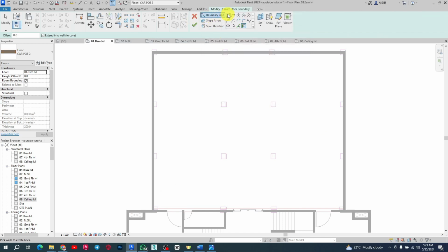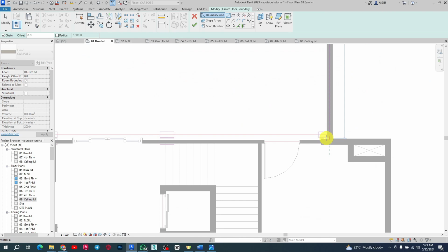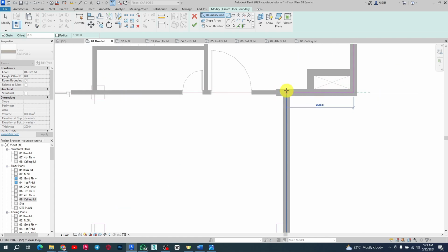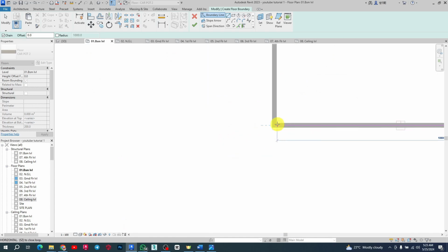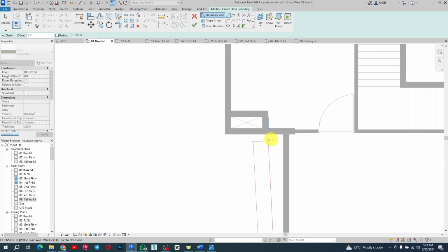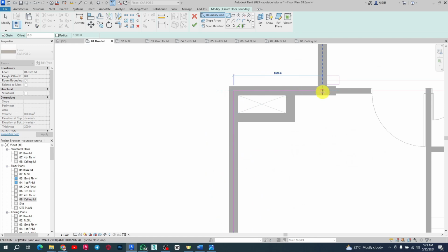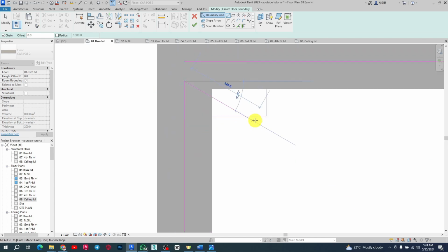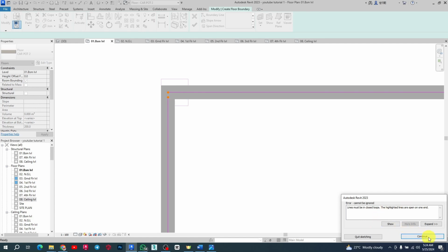So I'm going to go now to my line and sketch. So usually walls are supported at the center there like that. So I'm going to take this one right here, take at this different position, right? So draw all the way and you must close, and that is something with Revit. It's not like in other software where you can just draw and end it at a particular position and it calculates the surface and closes it for you. Here you must close it. If I drop it at this level, I've not closed it and I want to finish, Revit tells me that the line is not closed. So you want to go to highlighted area and join them.